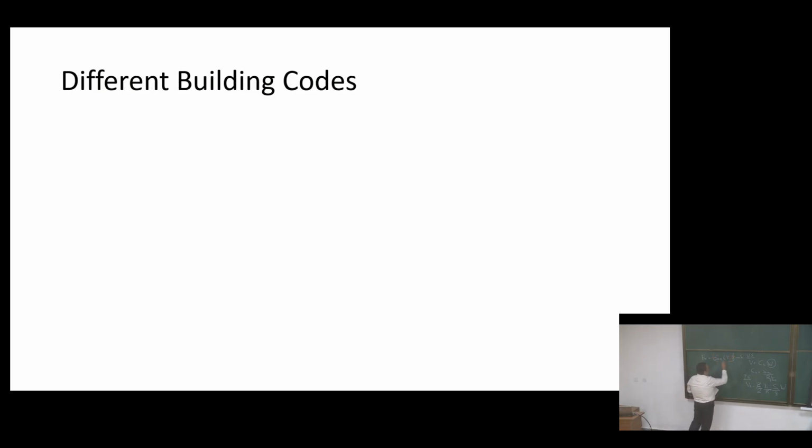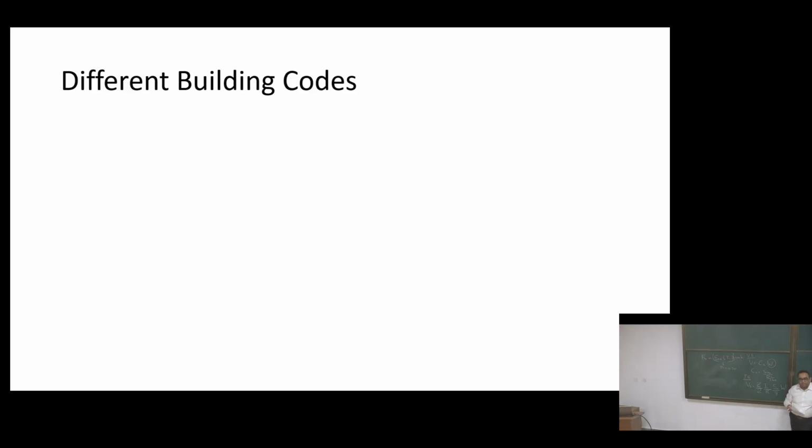Sd(T1) is from the design spectrum, m is the mass of the building, and lambda is a correction factor, either 0.85 or 1, depending on the case. In general, they don't have the importance factor and the seismic response reduction factor, but their design spectra is constructed a little differently than in other places.